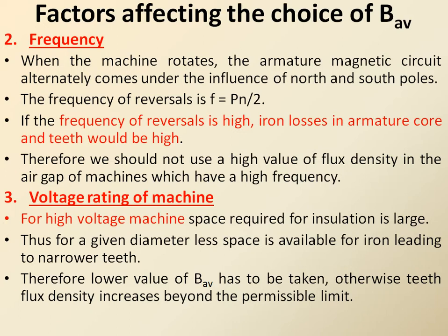Otherwise, if you choose a large value of specific magnetic loading, this will result in a large value of BT beyond the permissible limits, as the area of teeth is narrower.